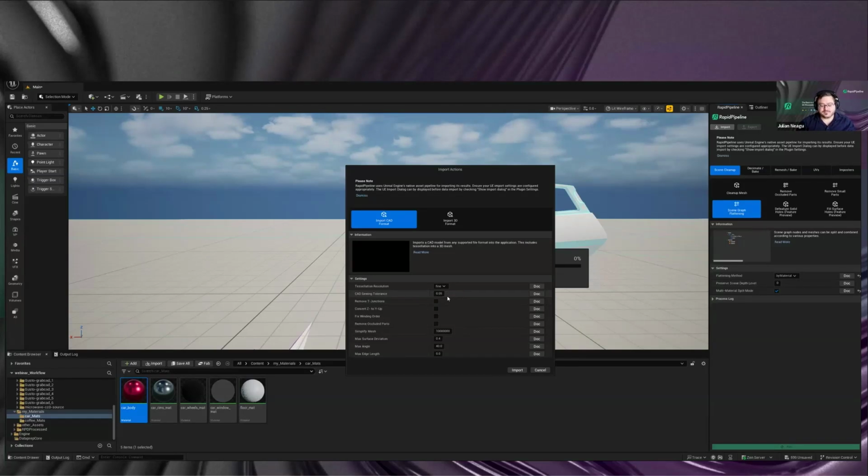And 0.05 millimeter is a very small distance, but usually that's enough to merge the different patches which might appear on the CAD side into a whole solid, so that we're doing that on the BREP, before the actual tessellation, so that we end up with better fitting topology. It's not to be confused with what I just did on the flattening side. That's a little bit different, but this is actually already happening on the CAD side, on the tessellation side.